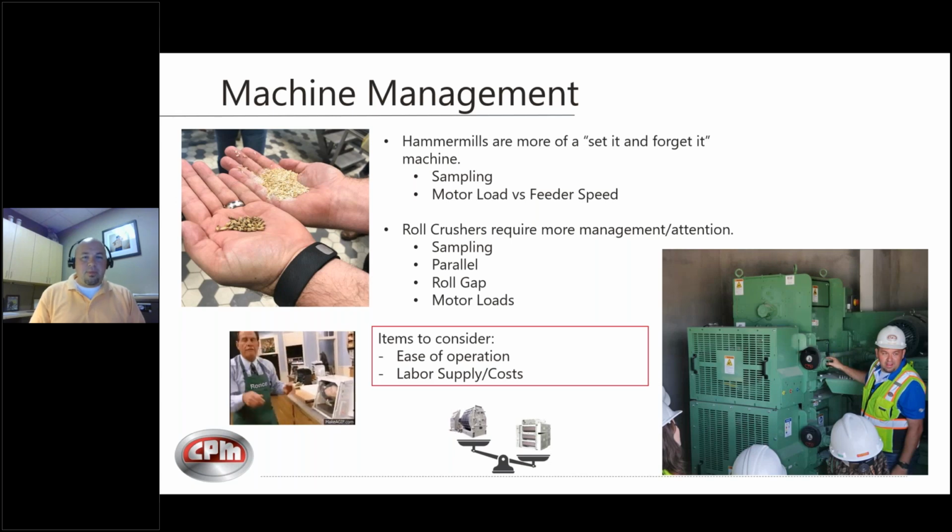So if you're a facility that just doesn't have a lot of manpower, you don't have the extra time to be checking on this machine and making sure it's set up the way you want, you might lean more towards the hammer mill instead of the roll crusher. Like I said, labor costs, labor supply, that's the big thing. If you don't feel like you have the quality employees that can maintain this, that's something you have to take into consideration.